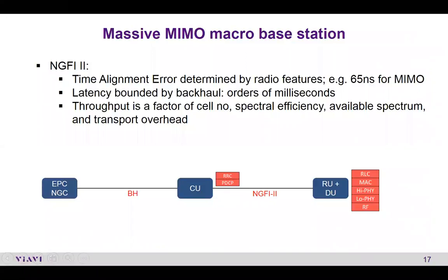So availability of a reference source is important to be able to measure time errors, especially when we get to that kind of measurement range below microsecond. Then we need a very good source and GPSs at both sides to make sure that we are measuring with the same reference, with same time of the day and same time and phase.